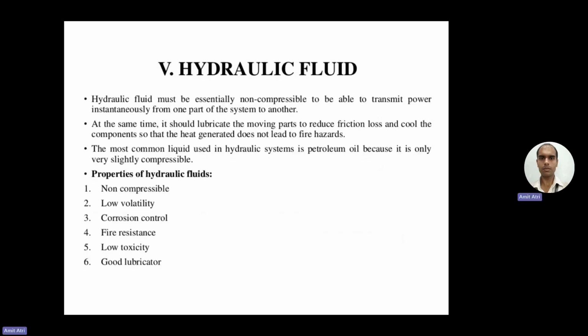Next is the hydraulic fluid. So hydraulic fluid must be essentially non-compressible to be able to transmit power instantaneously from one part of the system to another. At the same time, it should lubricate the moving parts to reduce friction loss and cool the components so that the heat generated does not lead to fire hazards.